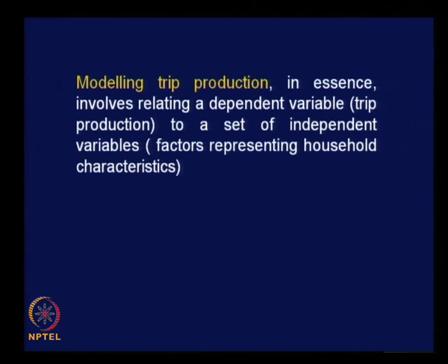Now, modeling trip production in essence involves relating a dependent variable, namely trip production, to a set of independent variables, namely the factors representing household characteristics as we listed, starting from the household size, number of employees, income, and so on.